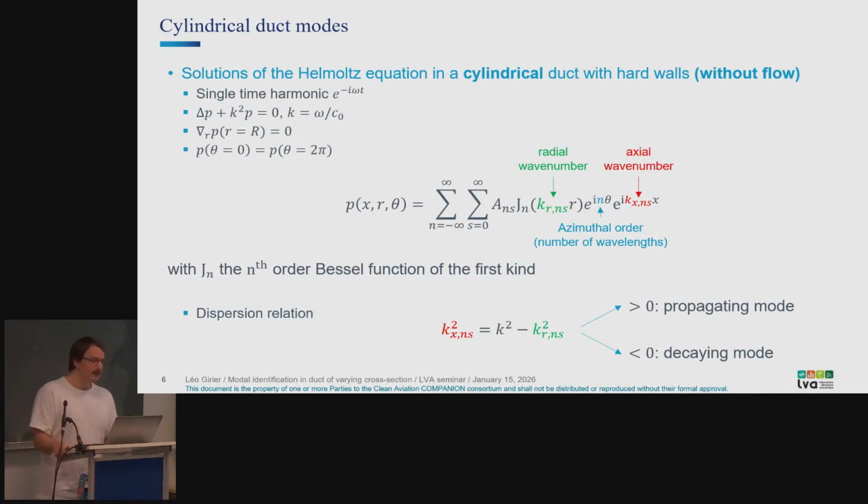But since I work mostly with analytical models, what I like to do is first try to simplify as much as possible and then add step-by-step layers of complexity in order to see how we can model a complex system. So to go back to the basics, just a quick slide to remind you of cylindrical duct modes. So here we will model a straight channel with hard walls and even without flow, okay?